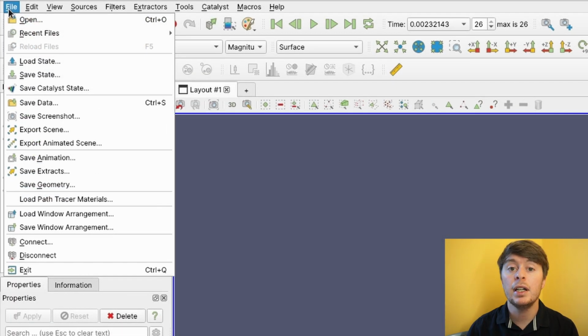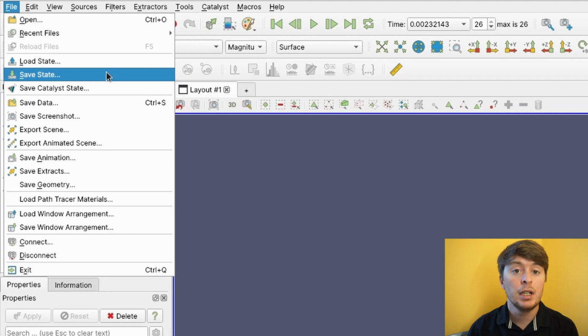And in case we want to take this and apply it to different models, because we're changing our inlet velocity, we can save this as a state. What this will mean is that we can change the underlying u.xdmf file, but keep all of those different filters we've just applied here. By doing that, we can then load up a different model and load in those filters we've applied.